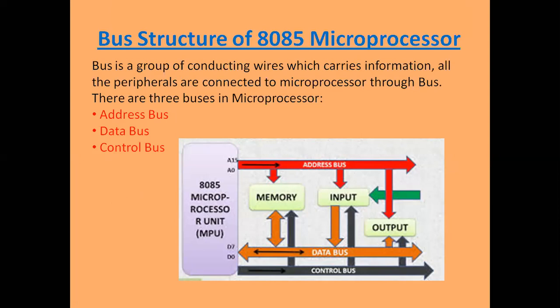And that tri-state mode is basically the high resistance mode. High resistance means resistance that opposes the flow of current. So it will not allow that signal to transfer to the peripheral. So only the address will transfer to the input device, not to memory and not to the output device. And this is done due to the tri-stated buffer.